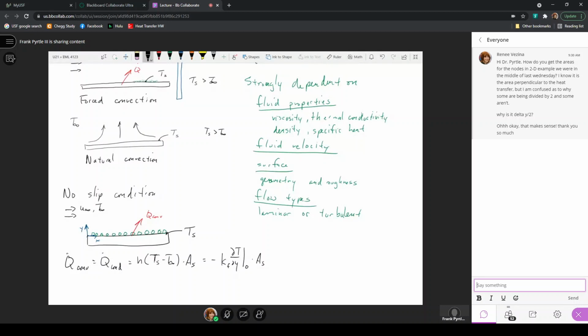So when defining this heat transfer rate by conduction through those molecules, it's the thermal conductivity of the fluid. And this temperature gradient is a temperature gradient that is in the fluid. There's a temperature difference that is required to support the heat transfer rate by convection, and there's also a temperature difference required to support the heat transfer rate by conduction through that stationary set of molecules.